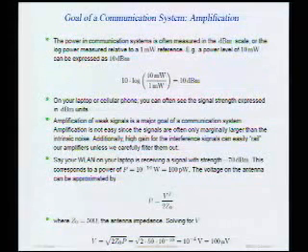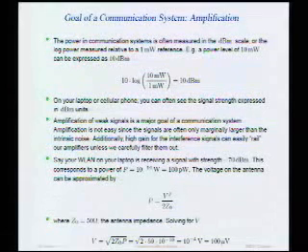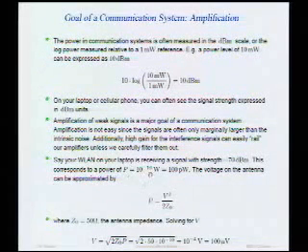Now, it's good to know that because almost all the communication equipment that you carry around with you, perhaps even today, has a little signal strength indicator, which is an estimate of how strong the signal is that's coming in. And if you look at your wireless LAN, you might find that a typical signal strength might be minus, let's say, 70 dBm. So if we take minus 70 dBm and just translate that into watts, well, that's 10 to the minus 10 watts, or 100 picowatts. It's not much power, is it?